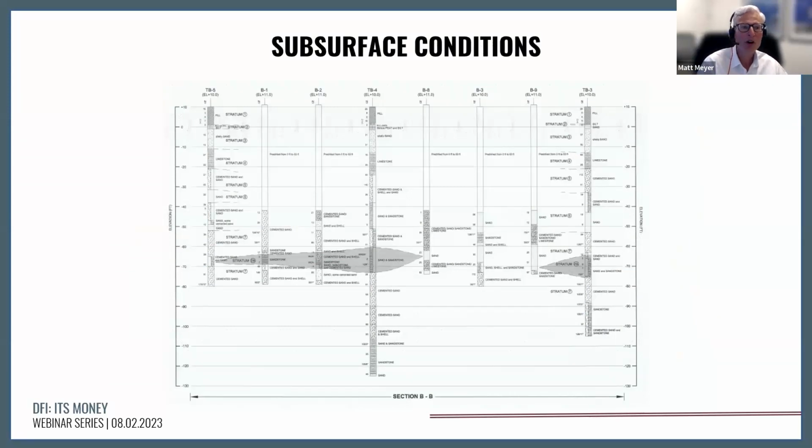I'll briefly talk about the subsurface conditions starting from the ground surface and extending deeper into the ground. Stratum 1 consisted of a layer of fill. Beneath that was a silty organic silt and peat deposit of various percentages of fines. That's our classical beachfront organic deposit that we see buried either underneath the fills or our beachfront granular soil deposits in this area of South Florida. Underlying that is stratum 3, which is a granular beachfront shelly sand. Below that is our first sedimentary rock layer that we encounter about elevation -10.